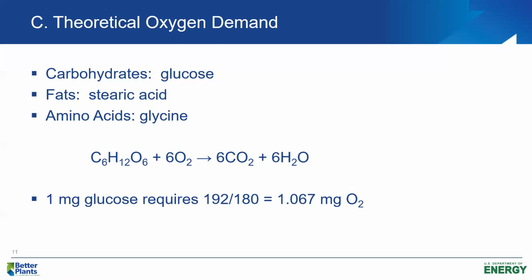And so what I told the treatment plant, based on how their plant was designed and the loading that they were receiving now, I said, look, you can take about 125 gallons per day of this whiskey, but it has to be bled into the treatment plant evenly over a 24-hour period so that you don't organically overload your treatment plant. They took the whiskey.